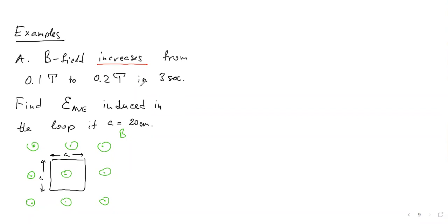We can find the initial flux and the final flux, take the change in the flux divided by the time. That would be the rate. Because this is one term, maybe we don't have to put N in this. And we can forget about the negative sign because the direction is a separate story.